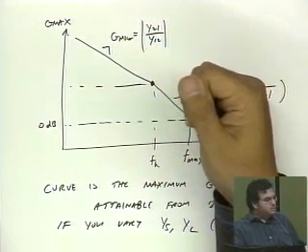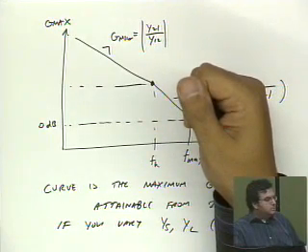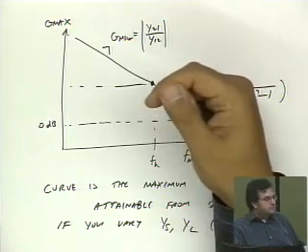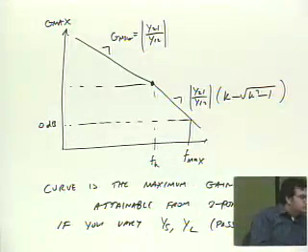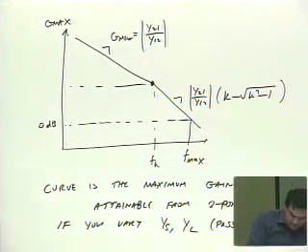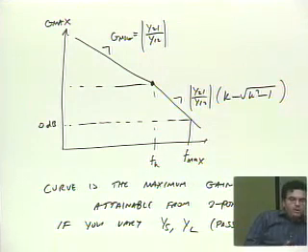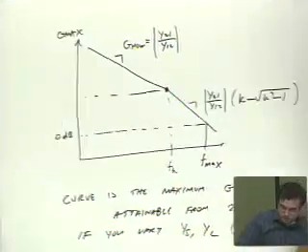Use passive elements? Are we allowed to use passive elements? You mean active elements? No, active. Possibly not allowed to use active elements. No, you're allowed to use any passive elements, right? So we try to unilateralize the... Okay, yeah, that's right. So up to now, we haven't used feedback, right? We haven't allowed for the possibility of putting feedback around the amplifier. So